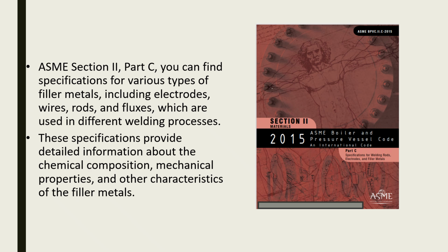These give you all kinds of detailed information about the chemical composition, the mechanical testing, mechanical properties, and other characteristics to produce the filler material. So this is basically a how-to recipe book for how to construct filler material. And not really how-to, but the criteria that it needs to meet to fall into a specific specification.